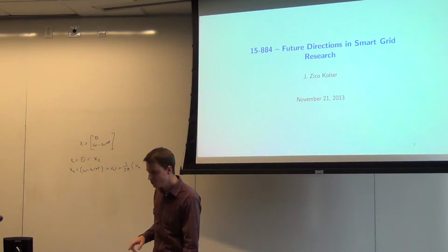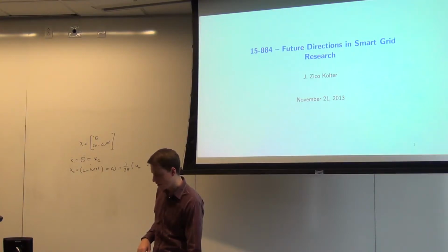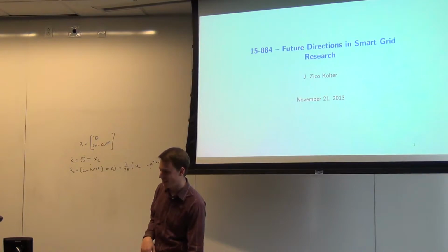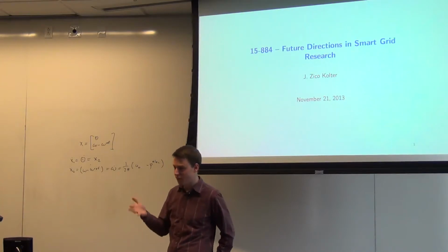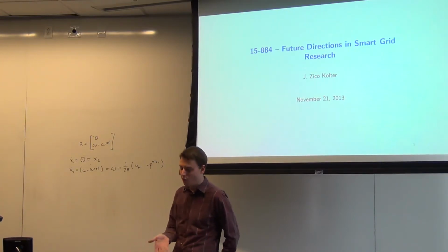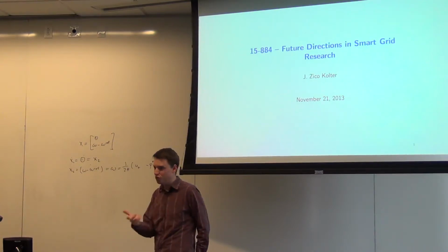Yeah? Do you have any insight into choosing the Q and R matrices for the LQR cost? Yeah, so the choice of Q and R is sort of the magic. This is the art of controller design, right? I talked about how great LQR was because it's optimal control instead of PID control, which is just gain tuning. But LQR involves plenty of tuning itself. It's just cost tuning. So you will tune the costs.